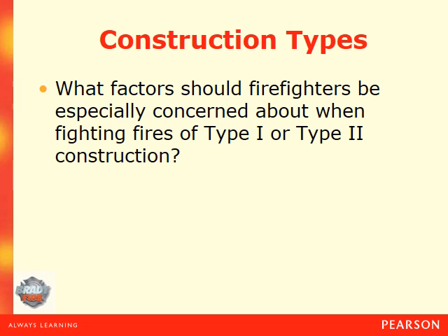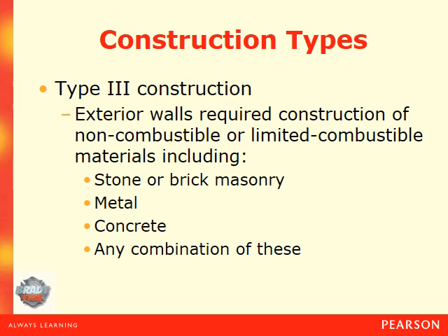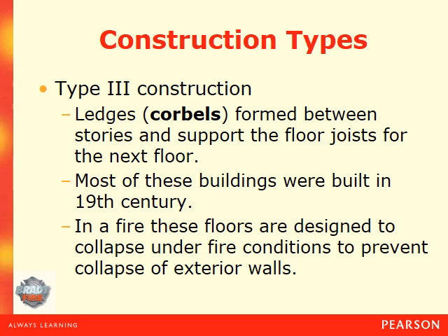So what factors should firefighters be especially concerned about when fighting fires in a Type 1 or Type 2 structure? So moving on to our Type 3 construction, which has exterior walls requiring construction of non-combustible or limited combustible material, such as stone or brick masonry, metal, concrete, or any combination of those. Again, I said this is one of those Main Street America type buildings.